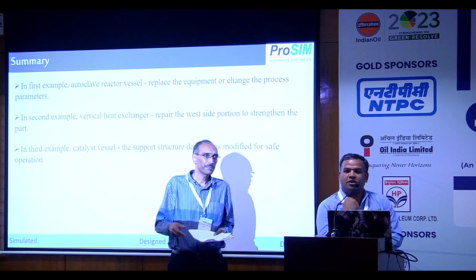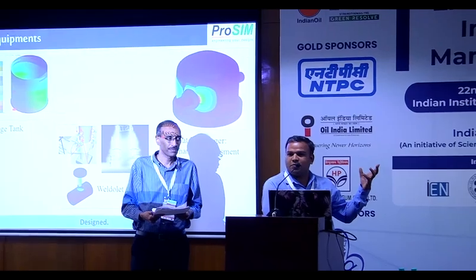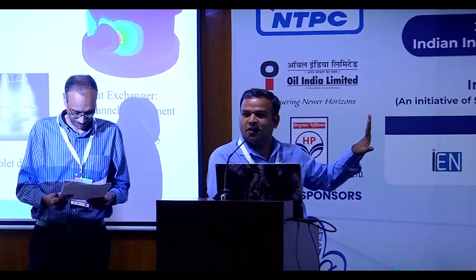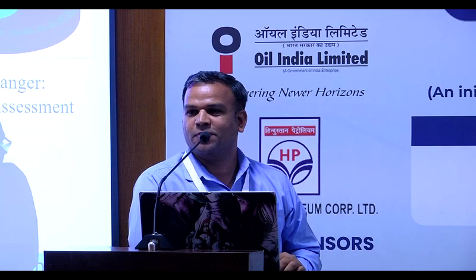So this is with the data captured by asset integrity. The life prediction, we have shown with the finite element analysis. For the integrity part, we can show whether the stresses are within the allowable, like membrane plus bending at the weld junction. So based on that, we can give the life, that you can run for this number of cycles.